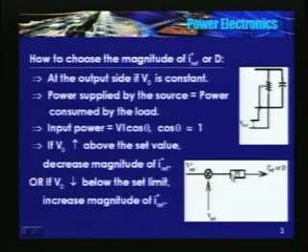I'll give it to a controller. Here I have selected a PI controller. P stands for proportional, I stands for integral. PI controller, because I have taken integral action so that at steady state error is 0. You might have studied this in your control theory. And the PI controller determines the magnitude of Iref or D. Of course, there could be another block also, maybe a saturator.